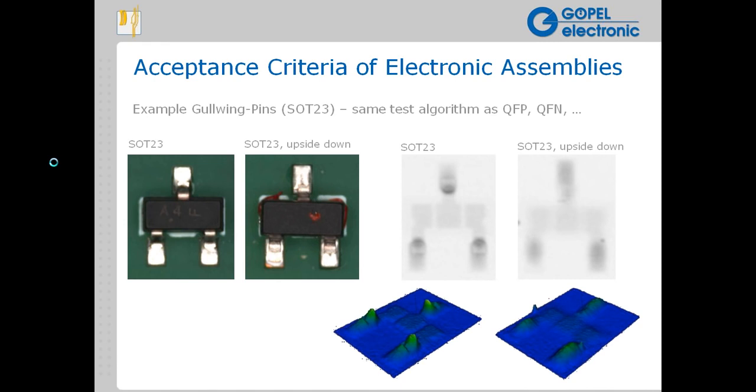To illustrate a little more relative to QFN pins, as you know, these pins can be somewhat challenging to inspect because the pin contacts are largely hidden. As you can see in this X-ray image, the forward meniscus is very clear. And again, with topo view, you can see a very dramatic characterization of the solder joint itself and the meniscus as it forms on the leading edge, the toe of the contact.